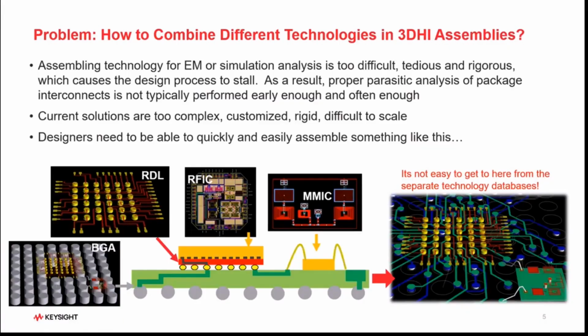The two big problems you run into with this type of 3D HI design: at first, it's just very complicated, combining different technologies together into one design. A lot of times you have scaling things going on. You have designs that may be done in microns being combined with packages done in millimeters being put on boards being designed in mils. You have different database resolutions between these three environments.